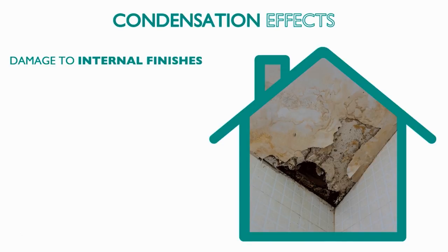Damp spots and any subsequent mould can be an indicator of cold spots, such as at junctions, corners or areas where there is substantial cold bridging. Surface mould can also be an indicator of poor airflow, such as behind furniture, at the back of built-in wardrobes or in specific areas in attic spaces.